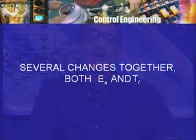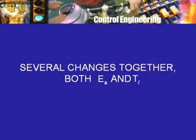Of course, one has to remember that the preceding analysis I talked about, changing EA and changing TL, etc., was very simplistic. Assume that EA remains constant and TL only varies, or TL remains constant and the applied voltage varies. These are just assumptions. In practice, it could happen that EA changes and TL also changes, and that the two changes conspire against you and therefore make the situation worse than it would be if there was only one change.